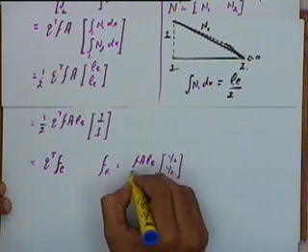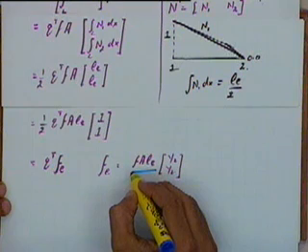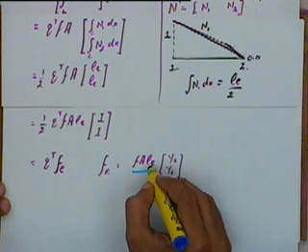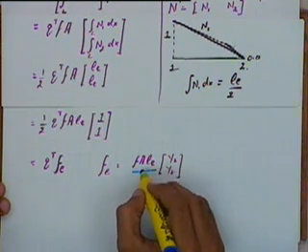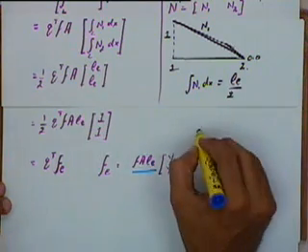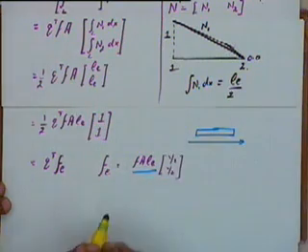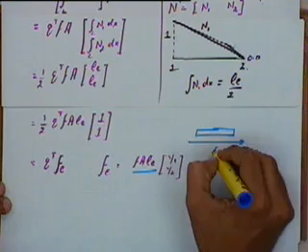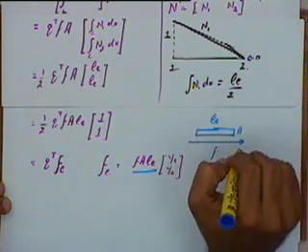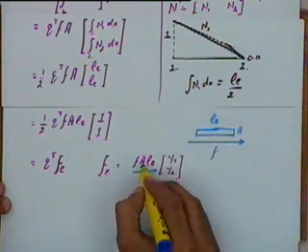Now what is F A multiplied by L E? F is the body force acting on the element, A is the area of cross section, L E is the length. So A times L E is the volume of the element. What is F times A L E? That is the total body force acting on that element. If I have an element like this that has some body force acting in this direction given by F, its area of cross section is A and length is L E. So the volume of this element is A multiplied by L E. The total force will be F into A into L E.